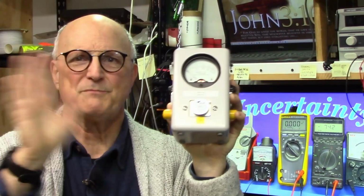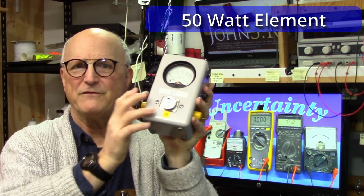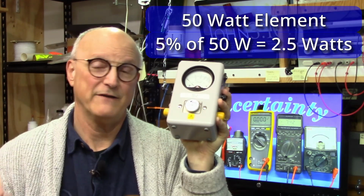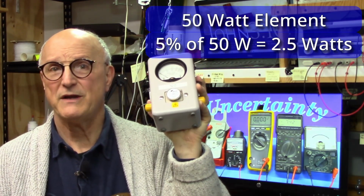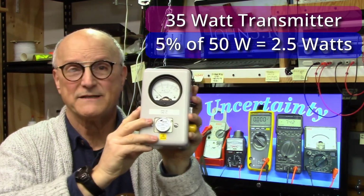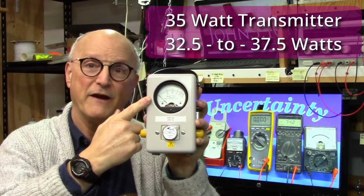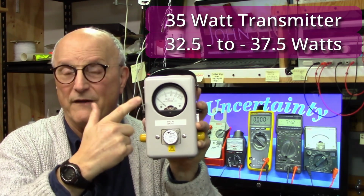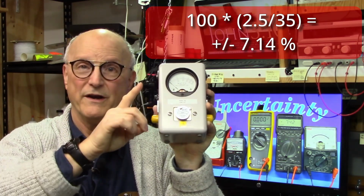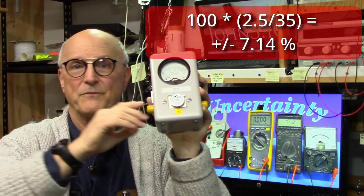Okay, so let's put this into perspective and see how this plays out in our measurements with it. Suppose I'm using my 50 watt element. Now 5% of 50 watts is 2.5 watts. Thus, if I'm measuring the output power of a transmitter whose actual power output is 35 watts, my Bird watt meter will report anything from 32.5 to 37.5 watts. On a 35 watt transmitter power, this amounts to 100 times 2.5 all divided by 35, or plus or minus 7.14%.